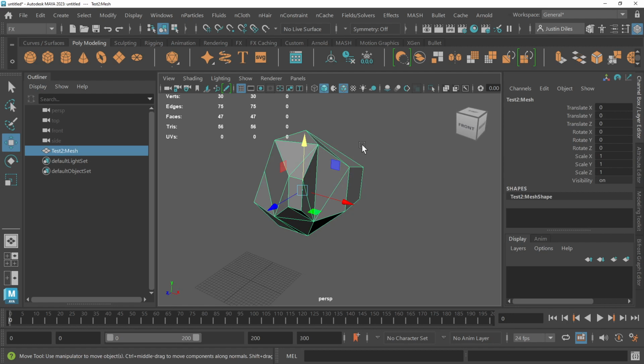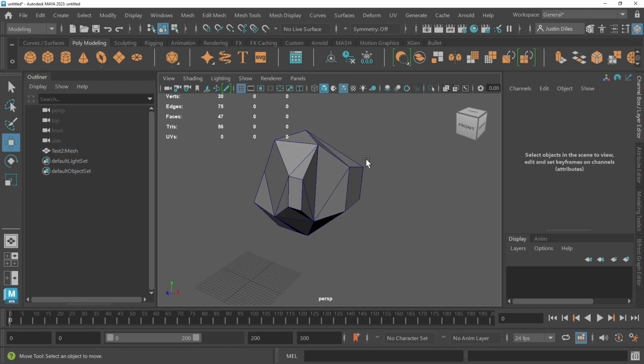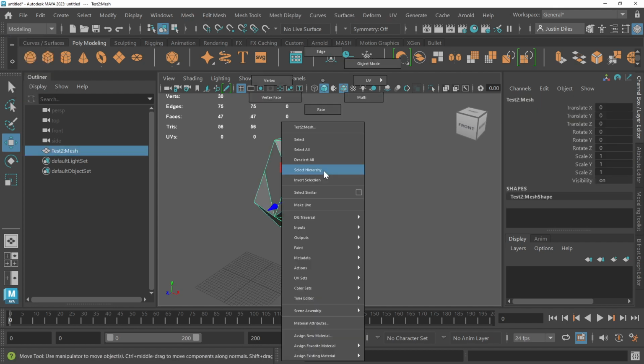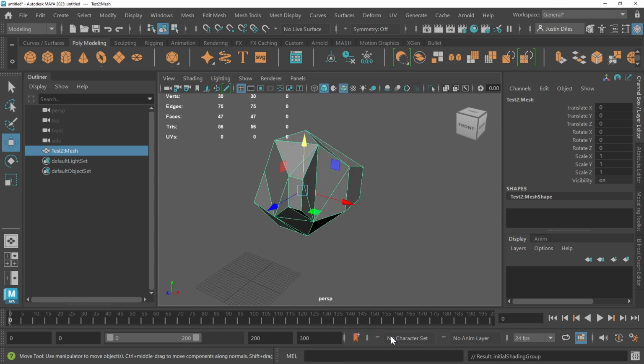So also, when we were looking at things in class, an object that I imported looked kind of weird, and there are a couple of things that can happen. If your object looks like the shading is not nice, the first thing you can do, and maybe always, is assign an existing material. The standard shader in Maya is Lambert 1. So assigning this material to your object is a good idea when it comes in from Rhino.